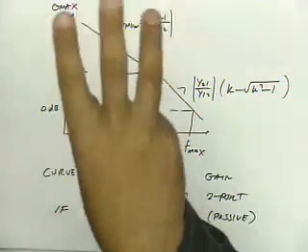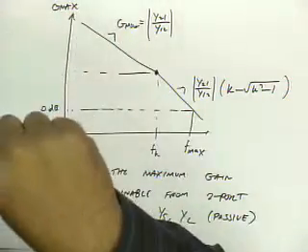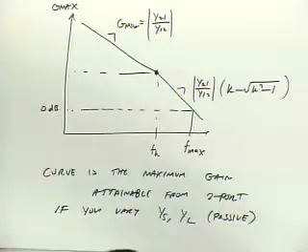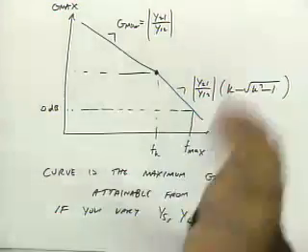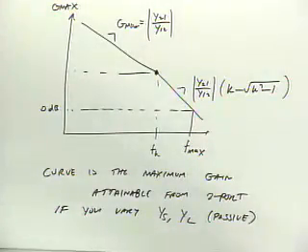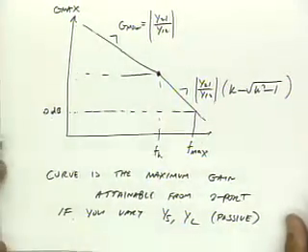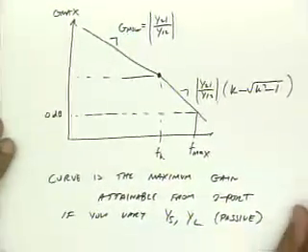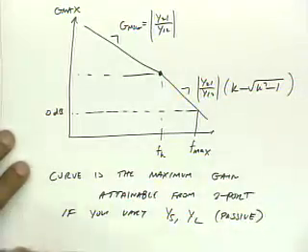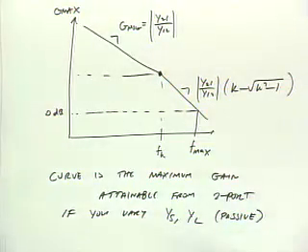So at very low frequency, your C mu is playing less role, but you have more gain in the device. Strictly at DC, you're right. The device is unilateral. Okay? Very good point. You guys will have a homework assignment where you'll take a real device and you'll plot K as a function of frequency and you'll plot these gains as a function of frequency and you'll get some intuition for it.